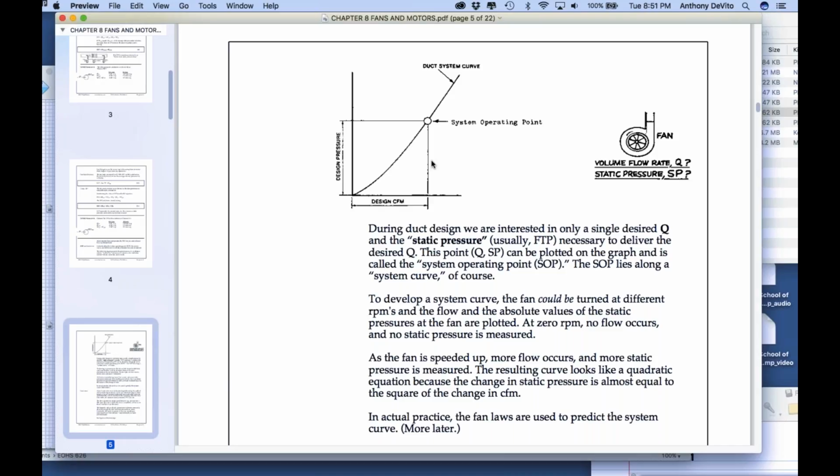So it's like a door, basically, right? Sometimes it's a flat piece of iron that slides down into a slot in the duct. That's called a blast gate, right? Sometimes it's a damper, which is louvers that look almost like Venetian blinds that you can open and close a little bit to change the amount of air that's flowing through, right?